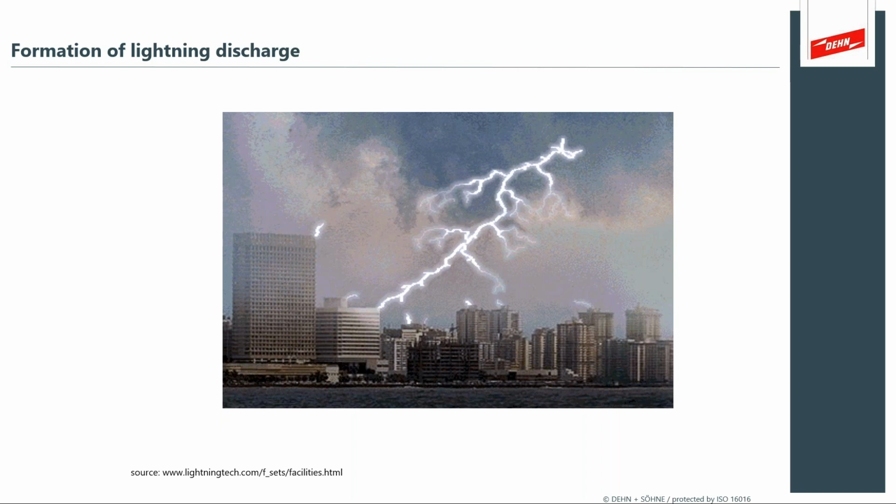Now, what can also happen is you'll see small little attachment points that didn't form the main ionizing channel. And then that main ionizing channel is what's described as the lightning bolt, and you get lots of charge moving one direction from the cloud into the earth, or from the earth into the cloud.